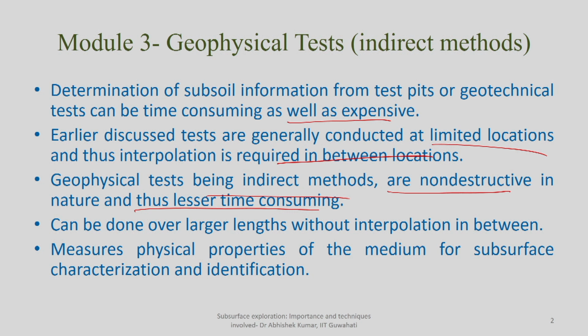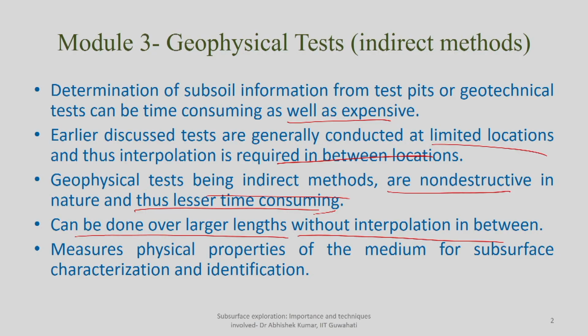what kind of soil properties are there below the depth at different layers, and depending upon what kind of depth you are interested to explore, you can go for different kinds of sources, you can go for different choices of receivers as well. So, these are overall less time consuming. It can be done over larger areas, because your sensors will be spread over larger area. You can go for tests even in 2 dimensions. So, you can go for these kinds of tests over larger lengths without interpolation, because that will consist of almost continuous recording. So there will not be much requirement for interpolation in between.